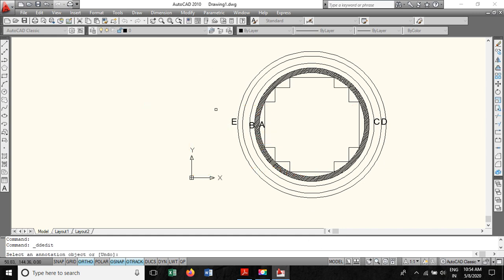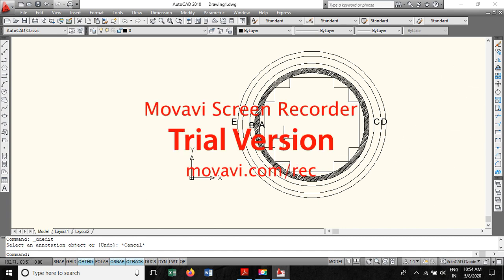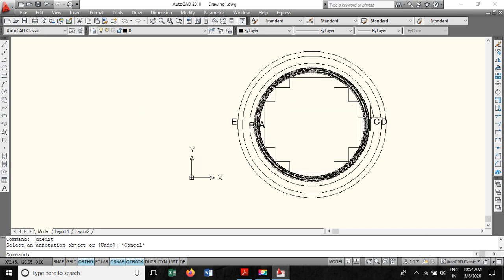So we have completed the sectional plan of one limb, where we have the 3-stepped core. A is the circumscribing circle, B is the inner LV, C is the outer LV, D is the inner HV, E is the outer HV.